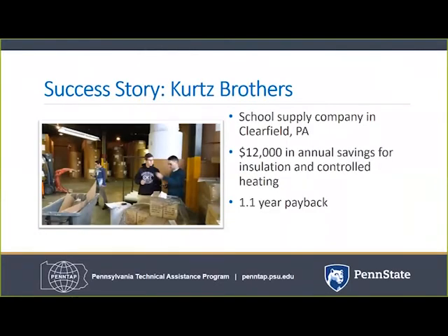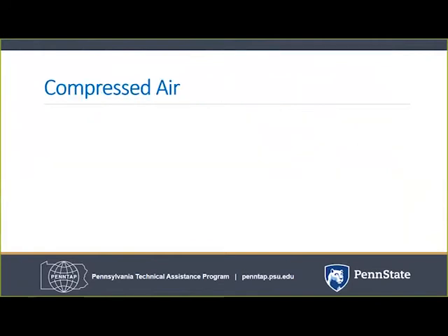Building envelope repairs and upgrades can also have short payback periods without large initial investments. PennTAP helped Kurtz Brothers, a school supply company, realize a total short-term annual savings of $12,000 by adding insulation and controlled heating, with a payback of just over 1 year. This discussion of building envelopes makes it clear that conditioned air is a valuable commodity.